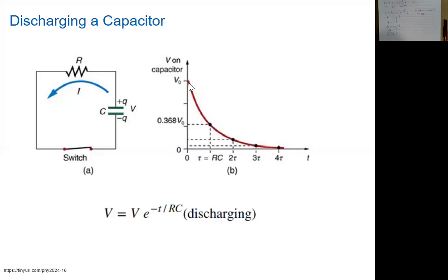Okay. And similarly, again, after about 4 times of the time constant tau, your voltage and charge will decrease to about 2 or less %. Okay, so at that time you can consider that the capacitor has been discharged. So for the voltage and then for the Q will be the same, exponentially decay.